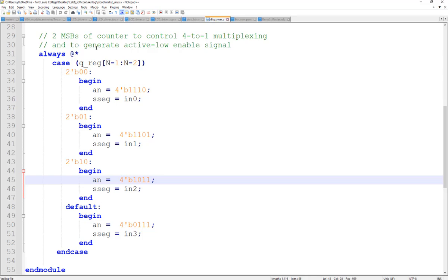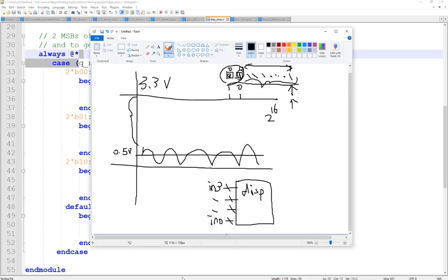So it's actually a counter. Why is that? It's because these are the 2 MSBs, and it's counting toward this one. Whenever it reaches this, it flips this bit. So it's basically the same code as when counter equals count max, like what we did, and then do something.